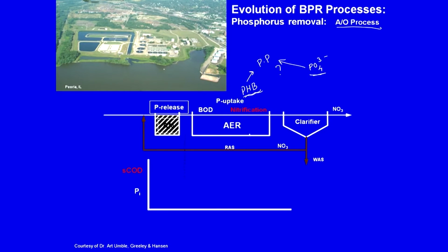So, what are the issues here? Phosphorus uptake, phosphorus release, let us see. So, COD is decreasing, fine. Why is this increasing slightly? Because as you know, in the anaerobic phase, phosphorus will be released when the polyphosphates are being degraded to give energy for formation of PHBs, right. And some of it is decreasing, not a lot of the soluble COD. Why is this? Fermentation products, and then they are being taken up by the microbes, or even for cell synthesis of some microbes. In the aeration tank, obviously kinetics is faster.